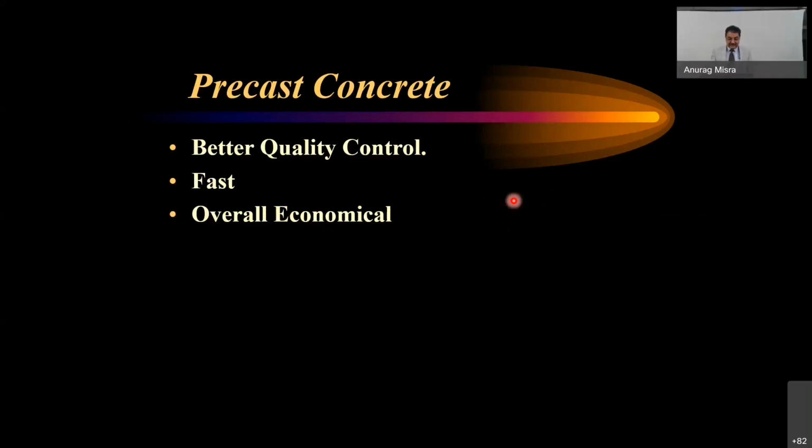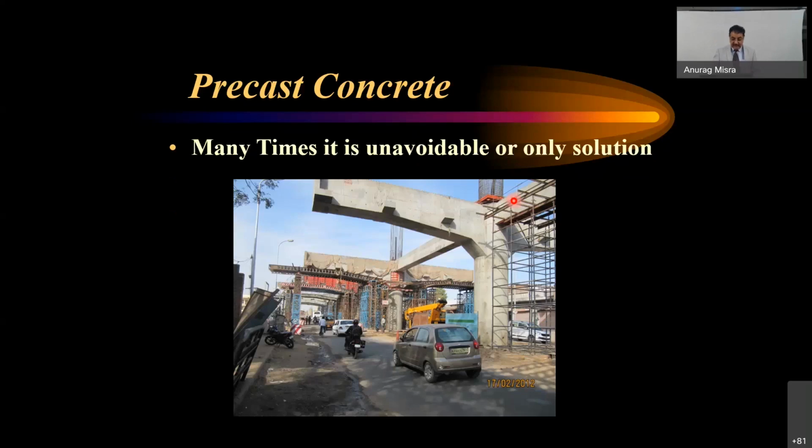So precast concrete, again, why do we want to go to precast concrete? I think these two go similar, because you are aware that if site welding is bad, site concreting is further, maybe multiple times worse than that. So in precast concrete, we have much better quality control. It makes things faster, and again I say that it makes it economical also, because when we are talking about the economy of either precast or pre-engineered structures, sometimes that's the only solution.